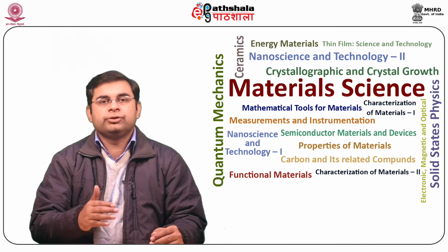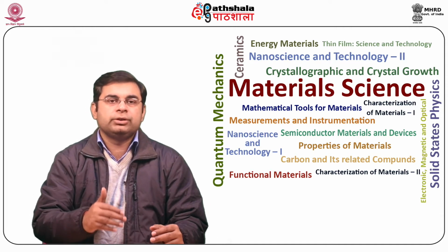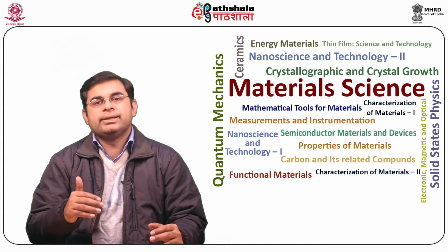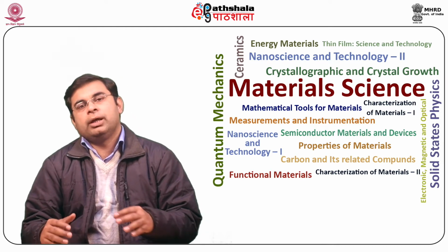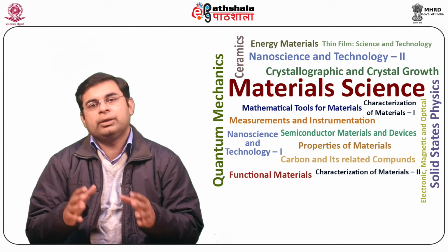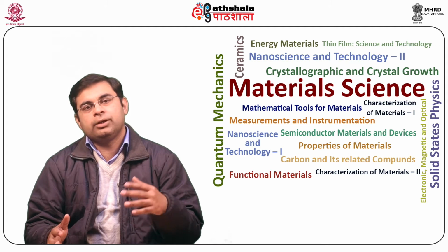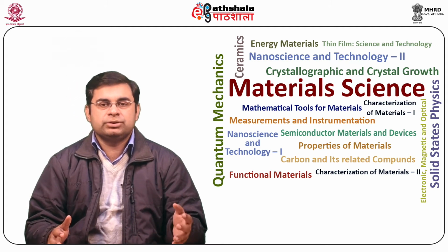Due to reverse bias breakdown voltage and reverse leakage current, conventional CV profiling is limited to a certain depth of Schottky diodes. It is crucial for evaluation of highly doped semiconducting layers, which are present in almost all basic and advanced device structures.